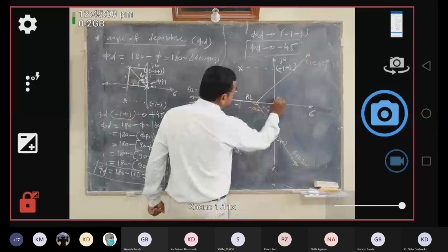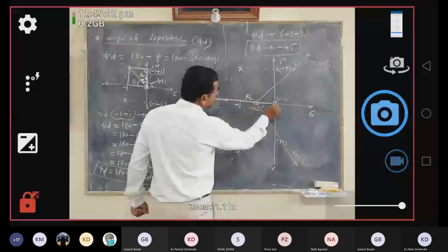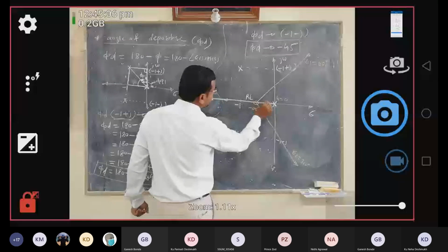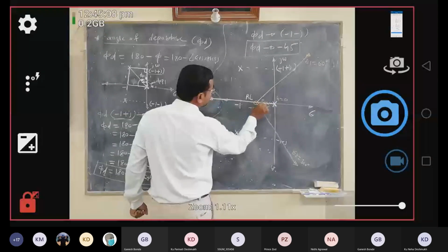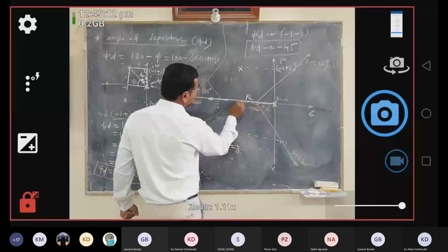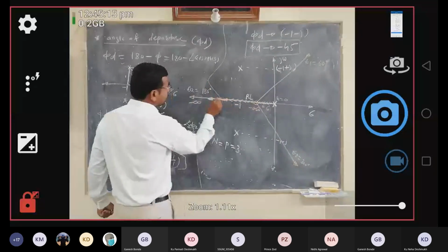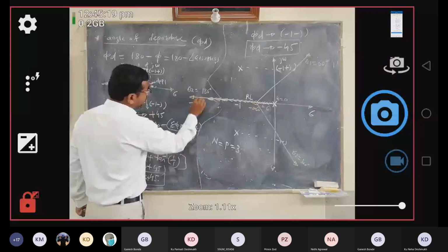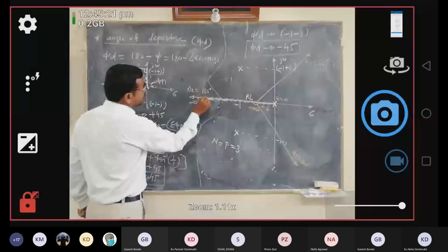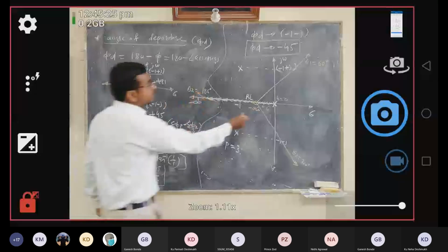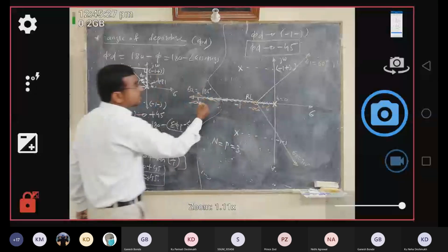At k equal to 0, the root locus branch originates at this pole, and it may move like this. This branch may terminate at infinity via this theta 2. That means this is your first root locus branch at different values of k.